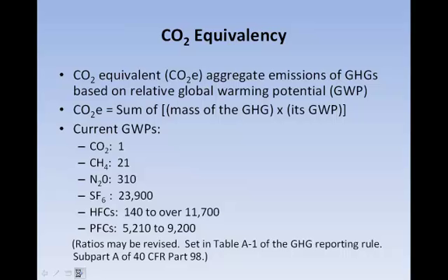In June 2010, EPA issued the Tailoring Rule, which addresses the applicability of PSD and Title V to greenhouse gas emissions. The rule can be found at the website listed on this page. The Tailoring Rule does not change the basic applicability processes of PSD or Title V. However, it does incorporate a way to determine if emissions are in an amount that makes greenhouse gases a regulated NSR pollutant, based on the level of CO2e emissions.